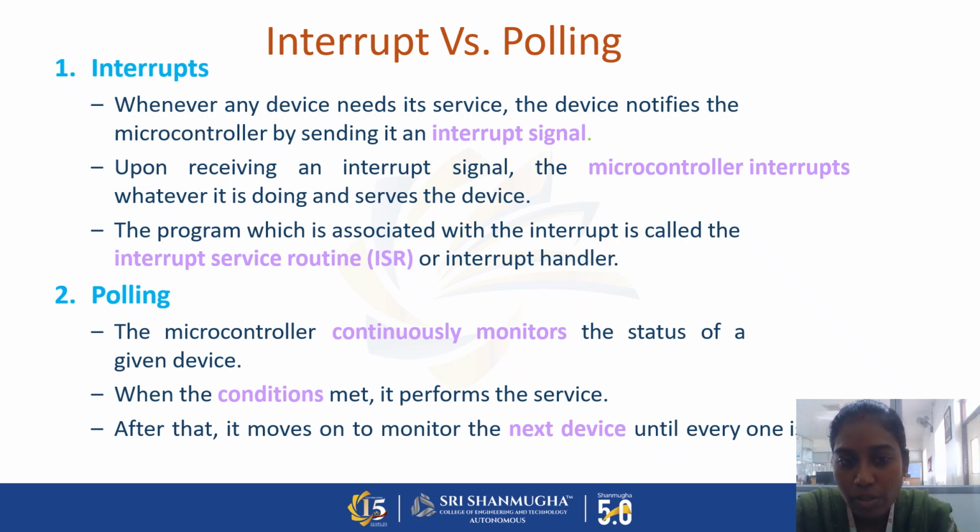The interrupt service routine has a priority table, so based on the priority, whenever an interrupt signal comes to the microcontroller, the routine calls upon the interrupts accordingly. Or else the interrupt service routine has a vector table of the interrupts, and based on the vector table it calls upon the interrupt signals. That is the interrupt method to handle interrupts.